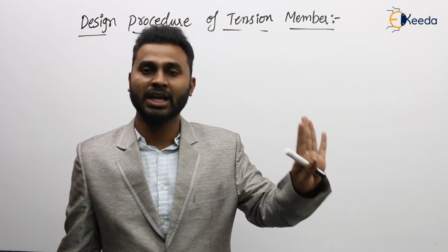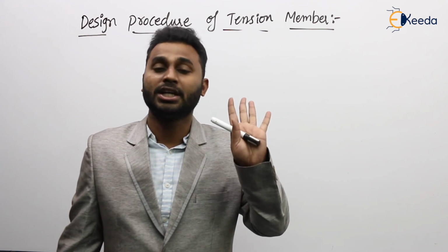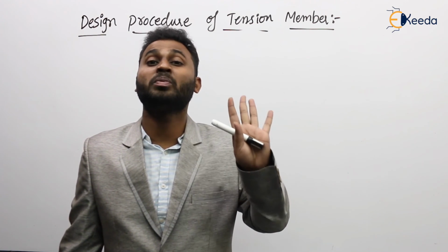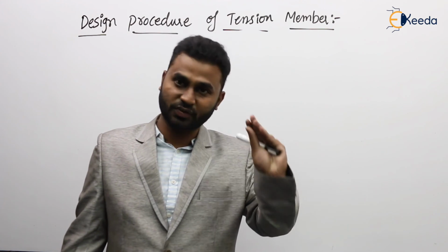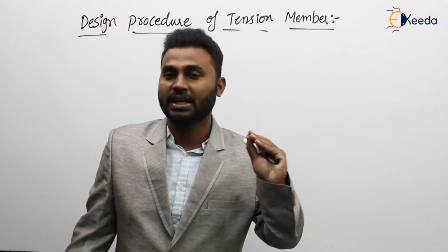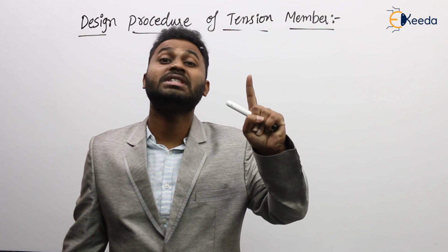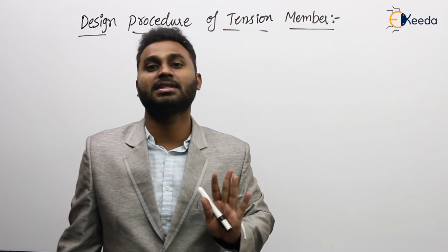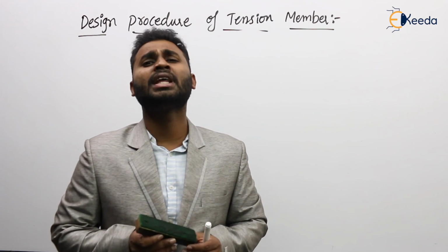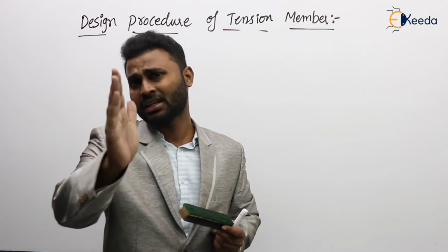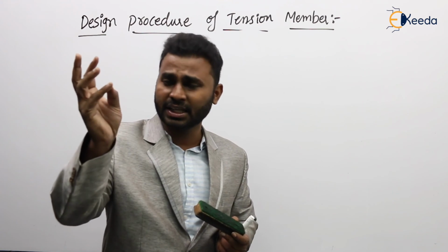But in a bridge truss, mainly I am talking about the bridge truss. Why? Because it is the truss which is subjected to major load. So that is our prime concern. If you see any bridge truss, truss girder or steel bridge truss, in that we are going to use channels or angles as members. So from the steel table, select either angles or channels.